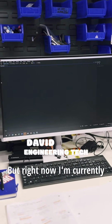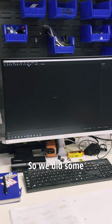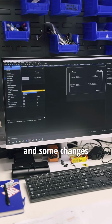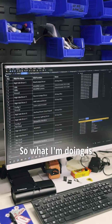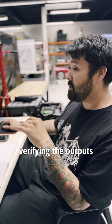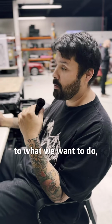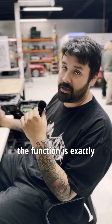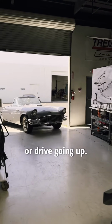But right now I'm currently going over the PDU outputs, the power distribution units from AEM. So we did some wiring changes and some changes to the firmware, so the outputs are different for the PDUs. What I'm doing is verifying the outputs and the pinouts on the wiring for the Thunderbird are correct and match up to what we want to do, making sure the function is exactly what we want it to be at a certain time of the vehicle, whether it be in wake or ignition or driving.